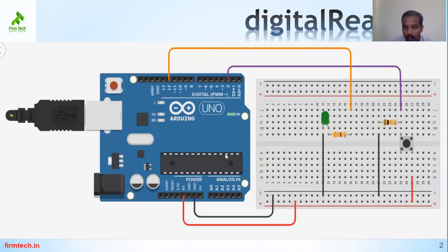This is the Arduino, and today my pattern of connection has also changed. See here, I have connected this ground to this rail, that is the rail with 30 pins or 30 points. As well as I have connected this positive to the positive rail. Whether it is a positive rail or negative rail is defined by us.